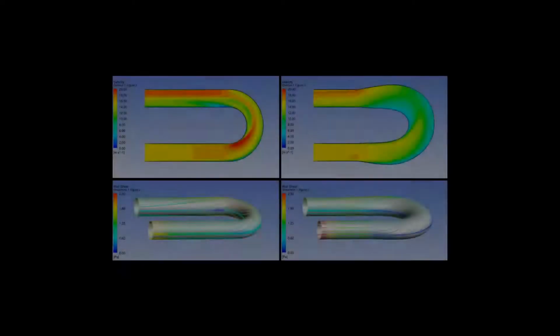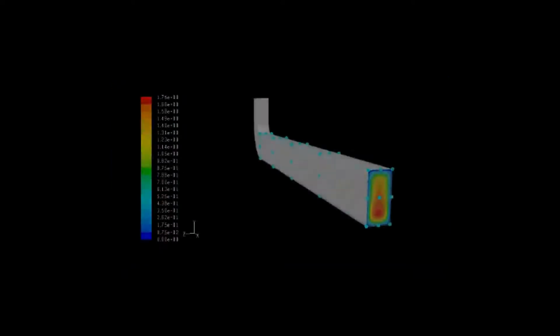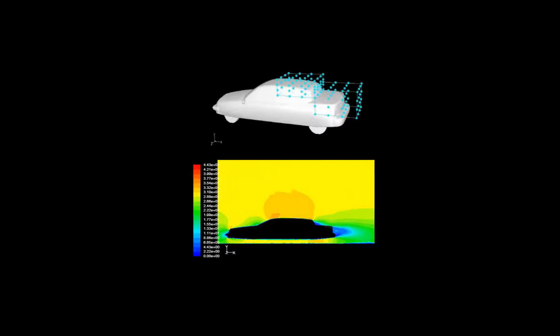In this video, I'll show you how to do a simple shape optimization using the Mesh Morpher optimizer in Fluent and design points in Workbench. You can use the Mesh Morpher optimizer in Workbench to solve shape optimization problems and improve design characteristics of your system. For example, you can improve flow uniformity in a duct system or minimize drag in a turbulent flow.